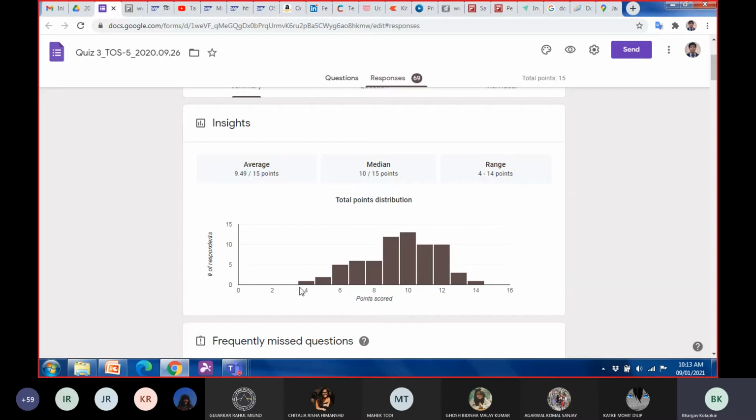Now, depending on this curve, I could set a passing percentage. So I would say that this is 5. So 5 is the passing percentage. Everybody who has scored more than 5 is pass, and everybody who scored less than 5 is fail. Similarly, when I say M40, it means that out of those 100, 95 of them have passed with a strength of more than 40 megapascals, and 5% have a strength of less than 40 megapascals. So that is what it means to have a compressive strength of 40 megapascals.